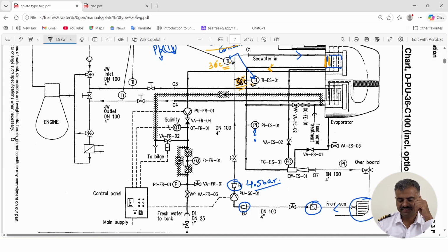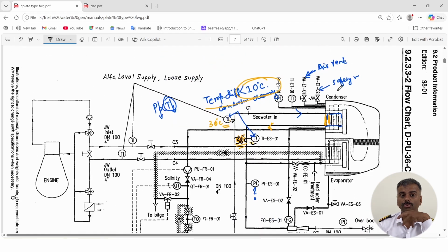The pipeline is getting pressurized, the plates are getting pressurized, the plates have started leaking and then seawater has accumulated. Or say your ejector is not functioning properly, brine is filling up, the vessel is UMS, nobody is seeing, the alarm is not coming, and the shell completely gets filled up. In that case, due to over-pressurization, the shell should not burst out.